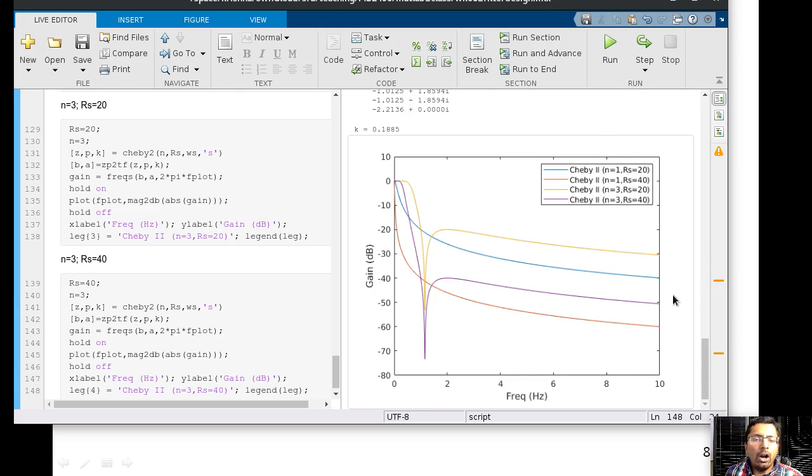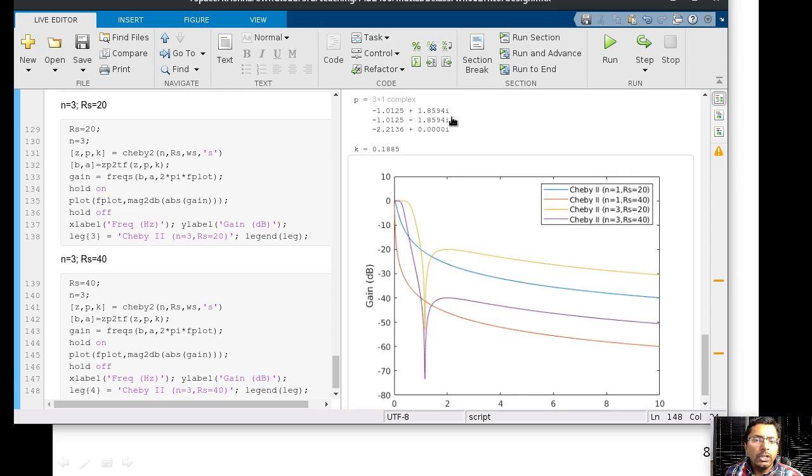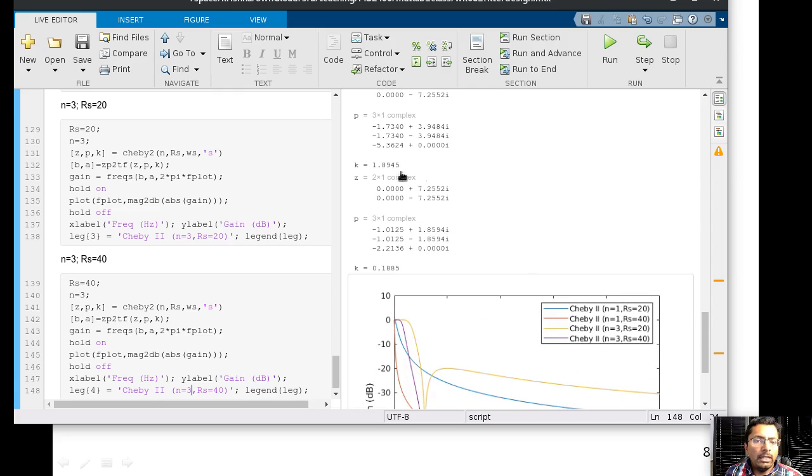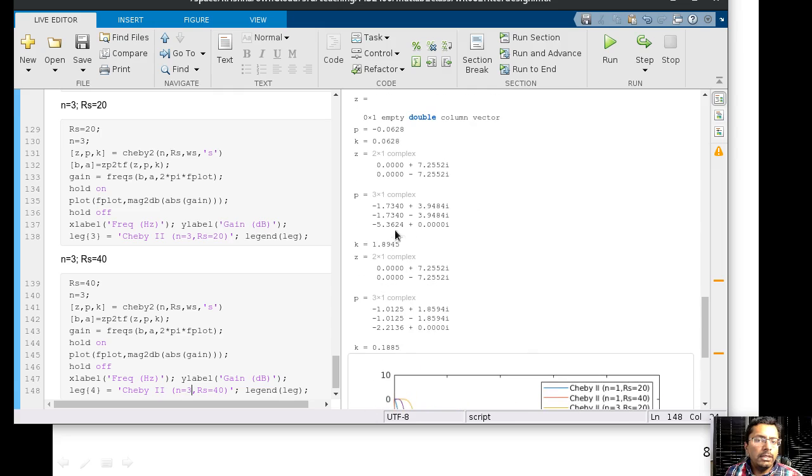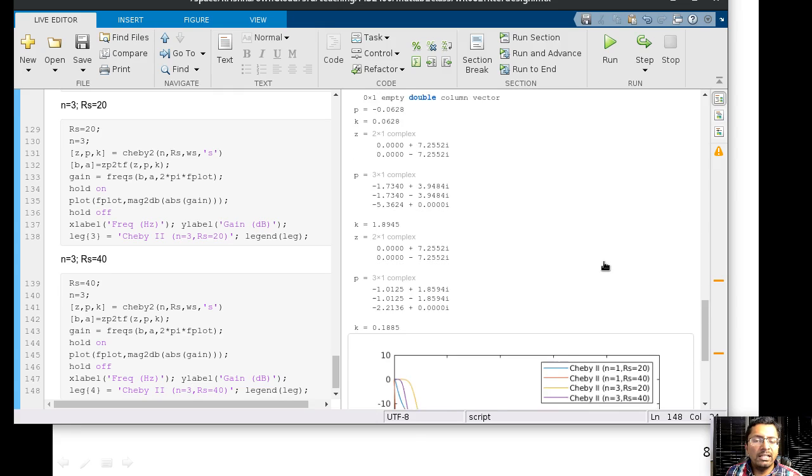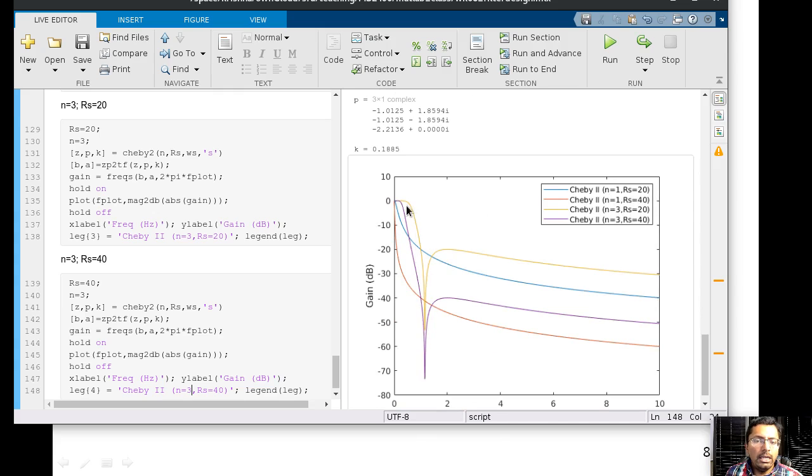So once we increase the order, things get a little bit more interesting, where it's able to add a few more things. So you'll actually notice if I scroll up that on top of the gain, it's actually adding some zeros to the system response. And what the zeros allow you to do is make the response a little bit faster, but then it comes back up. But I'm ensuring that the stop band attenuation is maintained, just that I can give a much quicker roll off to reach that particular value. Just that I can't actually control the pass band over here without changing the order.